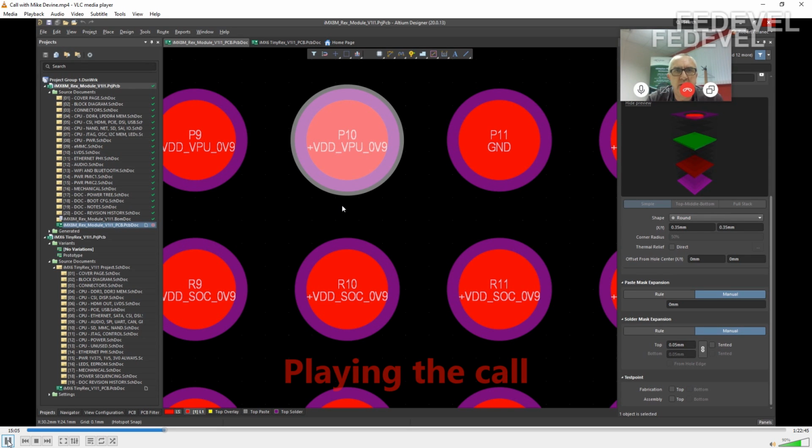Okay, so we'll just cover the resin fill and overplate option. Again, the minimum, it's really the aspect ratio of how thick the substack can go through. But our minimum drilled hole size for resin fill is 0.2, so 200 microns.